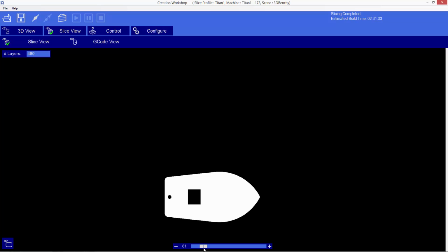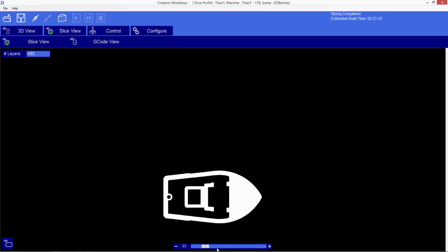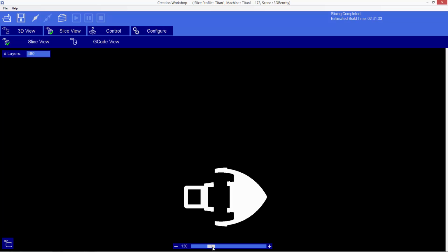And I don't want to see any solid areas appearing in the middle of nowhere, because that means that I have an unsupported area. Shouldn't have any of those, but you'll see that, okay, this is okay because the white area here was previously supported by here, so we're basically just reducing the surface area a bit. That's no problem. Let's move up.